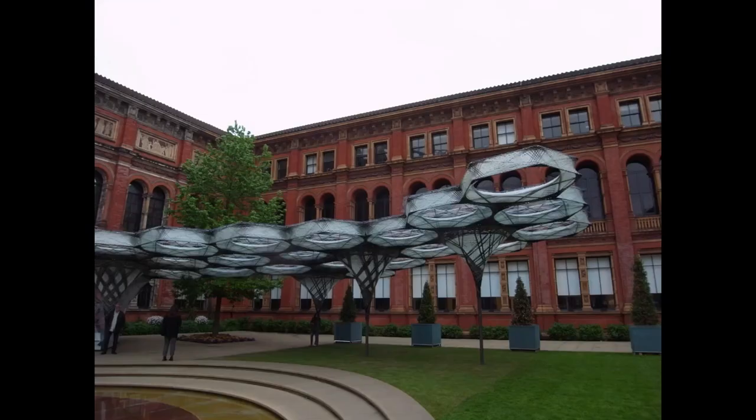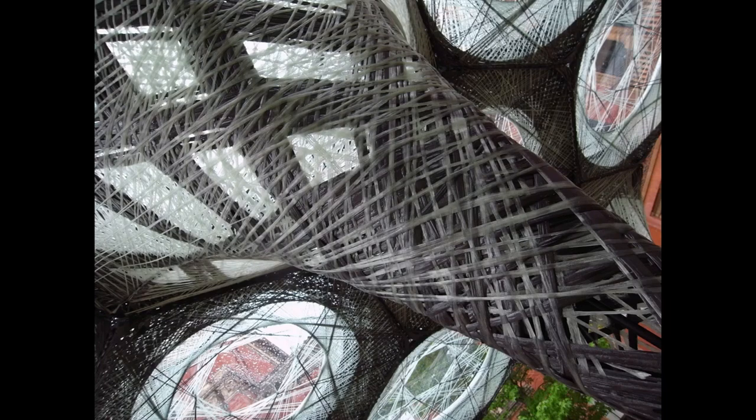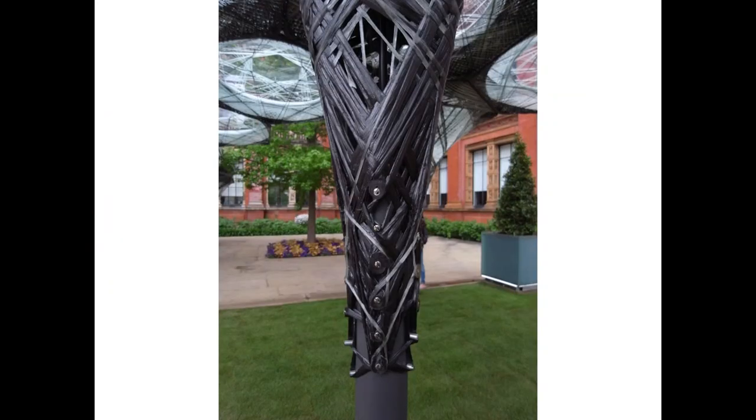I have to emphasize this. It's not a kind of Frei Otto structure. You can see there's no outliers. It's not a cable net or a suspension structure. It's not being pulled or pushed anywhere. It is mainly compressive, strangely, although it's made of lots of fibres. And I suppose in a way that's the beauty of it. You're using very light material to make a compression structure, aren't you?